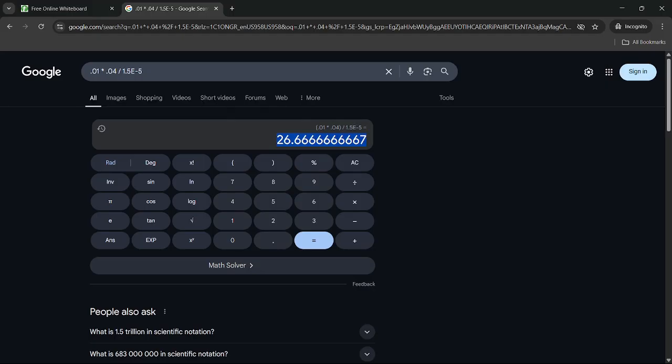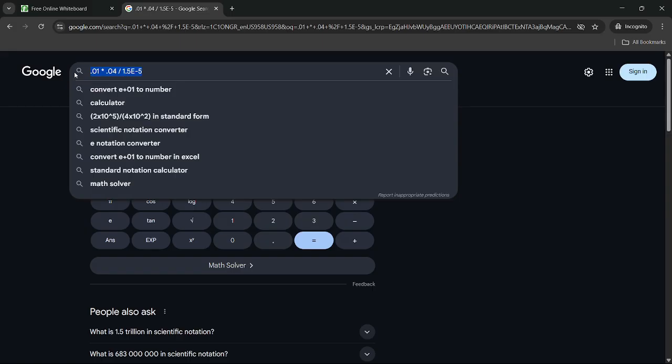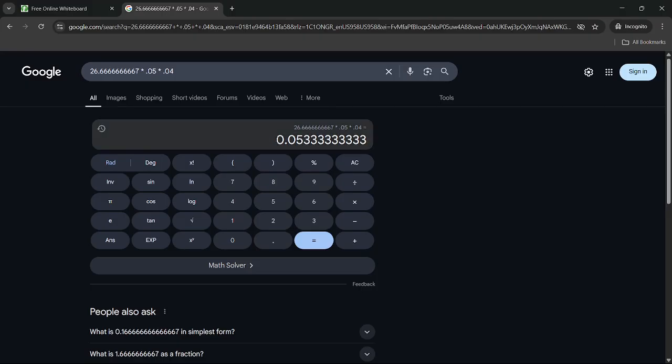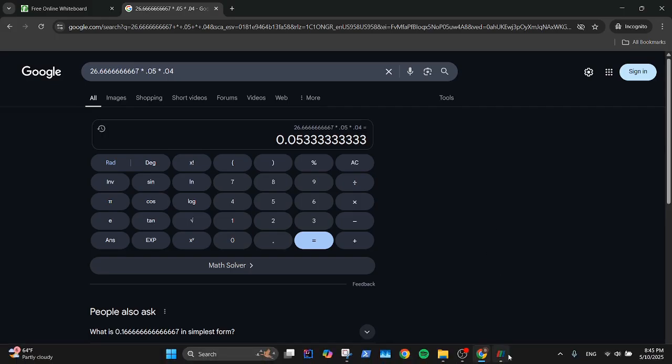So you can see we've got a relatively low Reynolds number, right? The requirement is for the Reynolds number to be below 2000. But it's not so low that OpenFOAM is going to struggle because our flow is too slow. And if we wanted to calculate entrance length, we would just take this number times 0.05 times, again, our diameter. And you can see our entrance length is 5 centimeters or 50 millimeters.